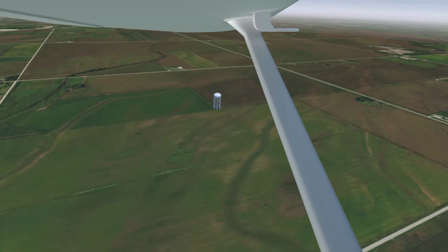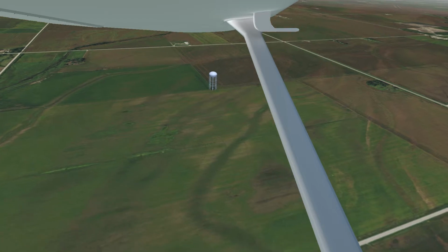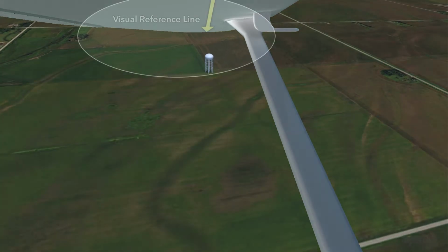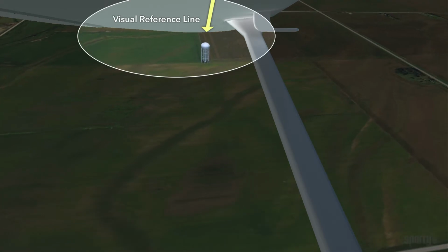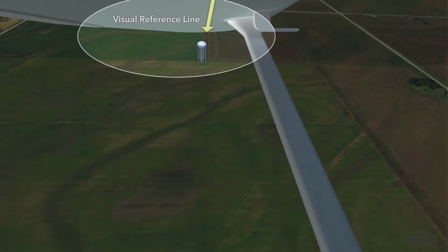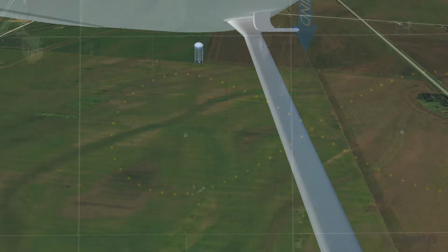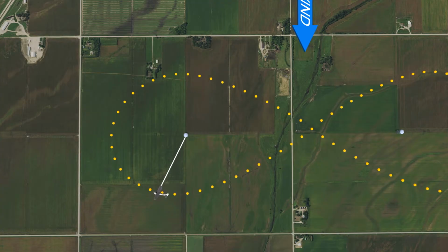8s on pylons rely on adjusting altitude and airspeed in order to maintain a visual reference line parallel to the airplane's lateral axis down to the pivot points. The airplane, if seen from above, would appear to pivot around the pylon as if it were tethered by a string to the pivot point.